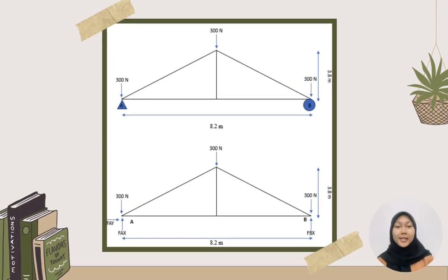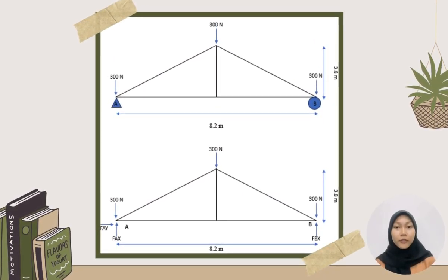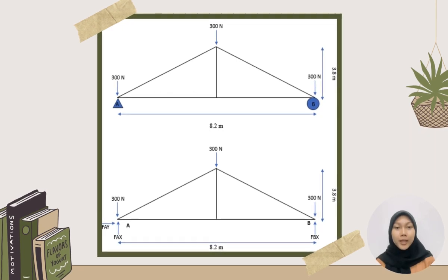Next, this is a free body diagram for the roof structure. The structure of this roof is supported by a pin and roller. The roof uses concrete tiles to be framed and supported. The frame will receive the self-weight load and transfer it to the supports, which are the pin support and roller support.